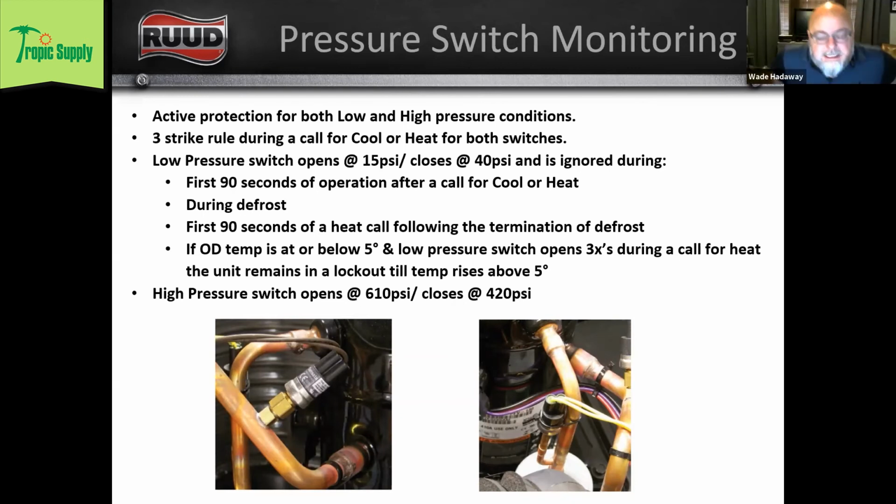Well, what's going to happen is, as we're switching and going either from steady state or from one mode to another, we're going to see some pressure imbalances, and it's possible that for a very brief moment we might drop down to 15 psi or below, and then it's going to start building back pressure up. What we don't want is nuisance trips that cause problems when there aren't really any problems, right?